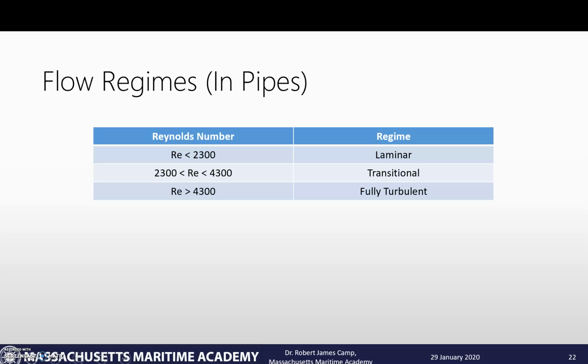And once again, the way that we calculate this is by using Reynolds number. So if we remember, Reynolds number is that balance of inertia to viscous forces. And so for pipes, we're going to be using Reynolds number sub D. Now what the sub D represents is a reminder, because remember, what is Reynolds number? Well, that was rho VL over mu, or VL over nu. That characteristic length, the length over which the interesting stuff happens.